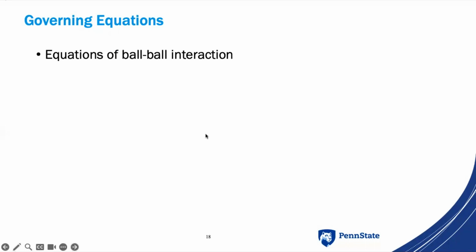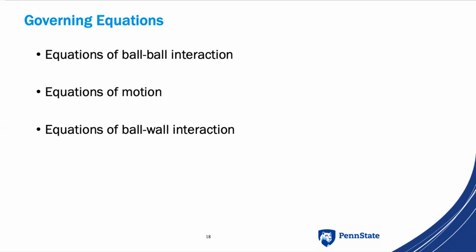I'm going to discuss some of the governing equations of the FEMDEM model, which is used to simulate the mechanical behavior of geomaterials. In the model, geomaterials are represented as discrete spherical particles that are bonded at the contact points, while the surrounding domain is simulated using finite elements. I will illustrate three main formulations. First, the interaction between particles or balls, then the equations of motion governing these particles, and finally, the interactions between the particles and the walls.